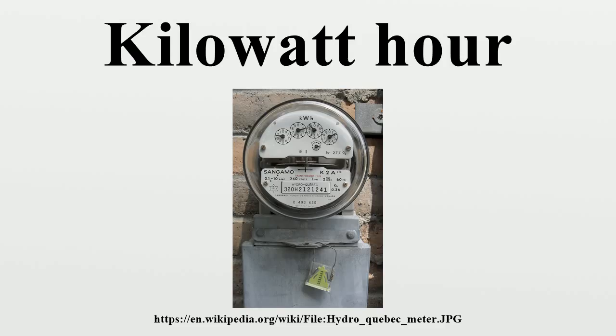Misuse of watts per hour. Power units measure the rate of energy per unit time. Many compound units for rates explicitly mention units of time, for example, miles per hour, kilometers per hour, dollars per hour. Kilowatt-hours are a product of power and time, not a rate of change of power with time. Watts per hour is a unit of a change of power per hour.